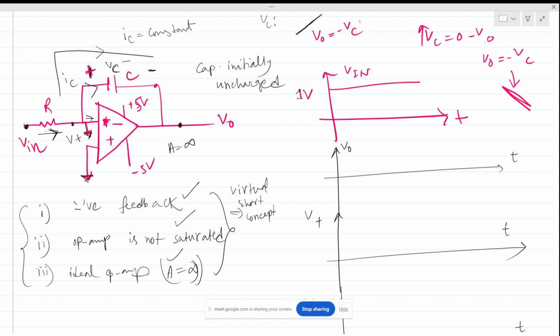This voltage is rising up. Another intuition I am giving to you: this node potential we are deliberately making 0, and a positive current is flowing through this path. So this node will be positive and this node will be negative. But this node is intentionally 0. So if this voltage is positive, this voltage must be negative, so that this terminal becomes positive and this terminal becomes negative, right? So this voltage becomes negative.